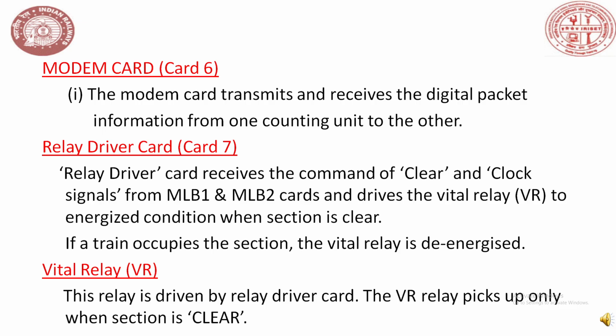Relay driver card, that is card number 7. Relay driver card receives the command of clear and clock signals from MLB1 and MLB2 cards and drives the vital relay to energized condition when the section is clear. If a train occupies the section, the vital relay is de-energized. Vital relay: this relay is driven by the relay driver card. The VR relay picks up only when the section is clear.